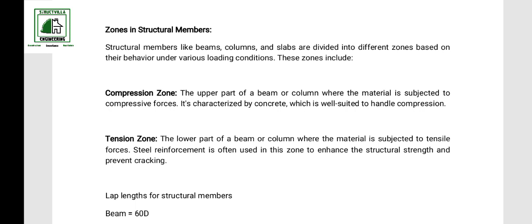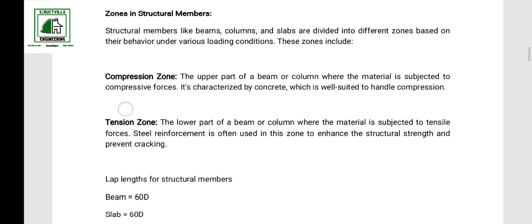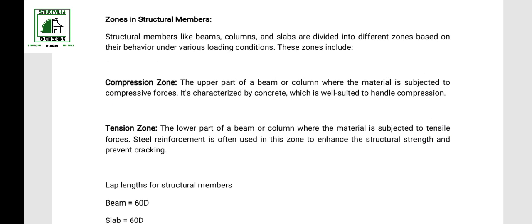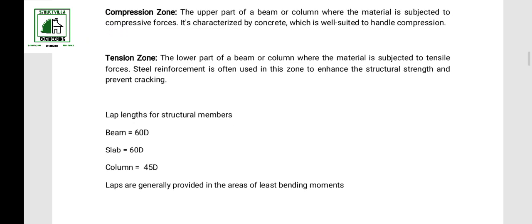That means if a concrete structure is able to carry a load of 10 kilonewton in compression, the tensile capacity should be 1, since the tensile capacity of the structural member is 1/10 of the compressive strength. So concrete has more strength in compression than tension. The reason we reinforce our concrete system is to prevent tensile failure, right?